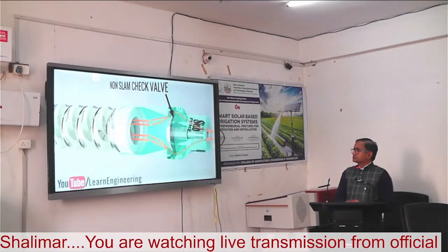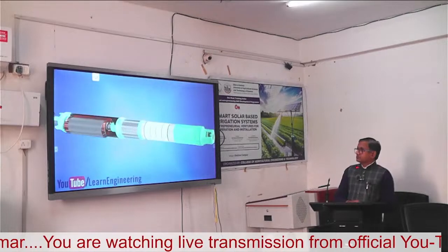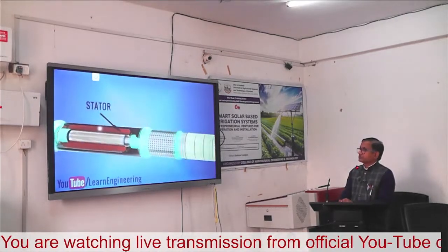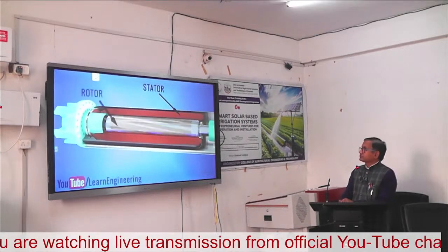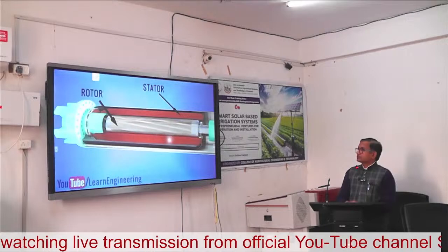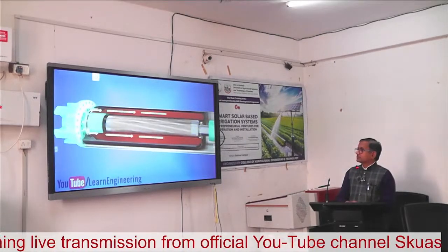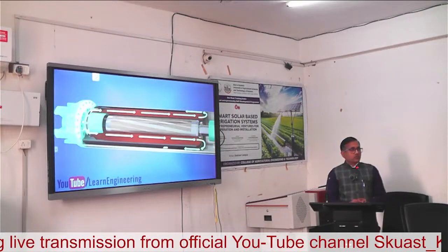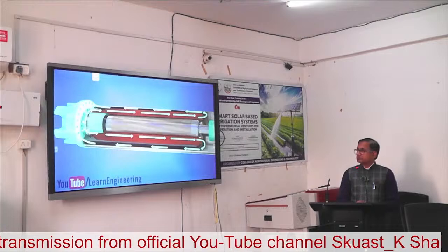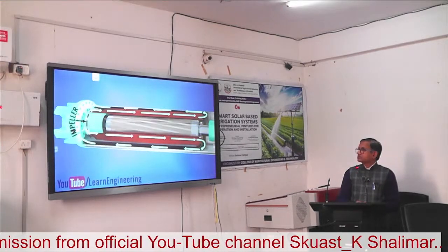Now let's focus on the prime mover of the submersible pump. Generally, an induction motor is used to run the impellers. The power supply to an induction motor is given to the stator, which can be either single-phase or three-phase. The motor produces a lot of heat during operation, and due to this reason, the motor is either water or oil-filled for effective cooling. The continuously circulating coolant jacket around the motor makes sure that the motor never overheats. You can see how a small impeller at the bottom maintains this circulating flow of coolant.